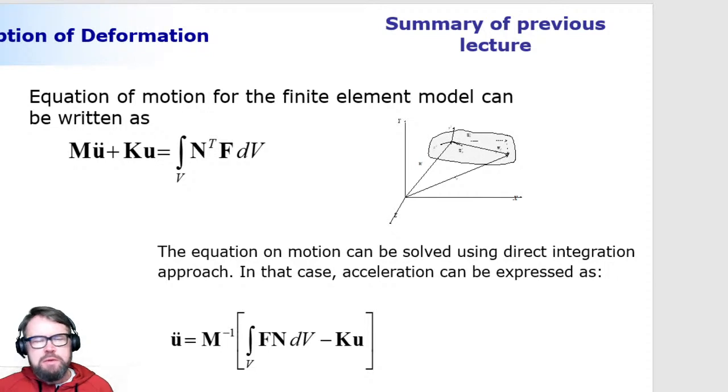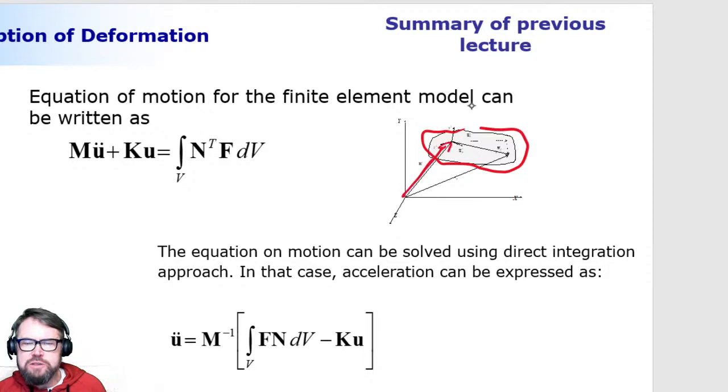Now, remember where we started the whole story. The whole story started from the need to describe the deformation of a body in a multi-body system. And we decided that this time we wanted to describe the deformation in a very elegant way by modifying the kinematics. Remember that in multi-body system dynamics, the first thing we do is describe where the body reference coordinate system is located with respect to the global coordinate system. That is described by vector R.